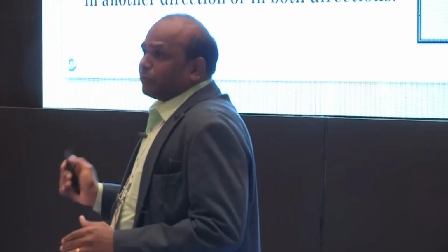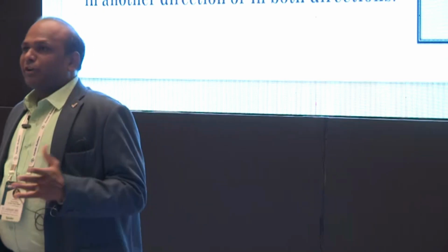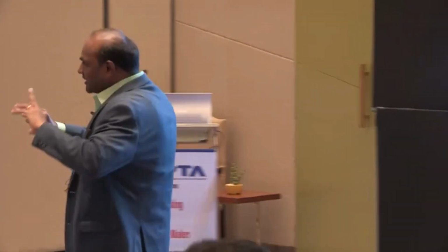In twin wire formers, this is where the invention came, because for example you are running a wire part. Now the wire length is around 50 meters, for example, and you would like to increase your machine speed. Okay, double. For example, it is running at 200 meters per minute, and you are going to increase it to a 400 meter per minute machine. Then what happens to the wire part? Can the same moisture be achieved at the end of the couch roll? No.